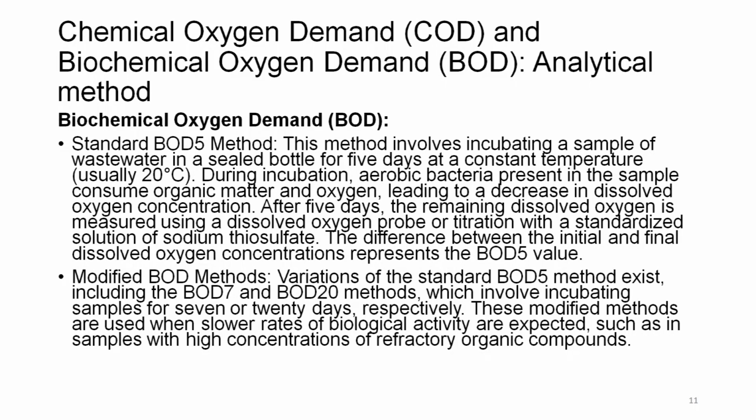concentration. After 5 days, the remaining dissolved oxygen is measured using a dissolved oxygen probe or titrating with a standardized solution of sodium thiosulfate. The difference between the initial and the final dissolved oxygen concentration represents the BOD5 value.